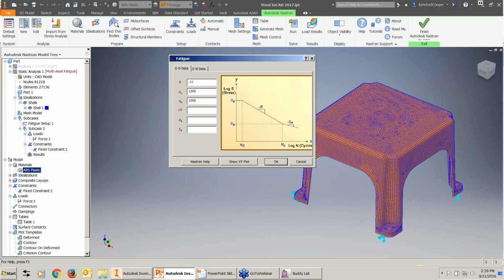The way we're going to be running the software is going to tell us that endurance limit based on our material conditions. And then the secondary slope is normally near 0, if not 0. And then lastly, material finish, corrosion resistance, other factors like that that could either strengthen or weaken the material. Again, all of this data is available at MatWeb and other resources like that.